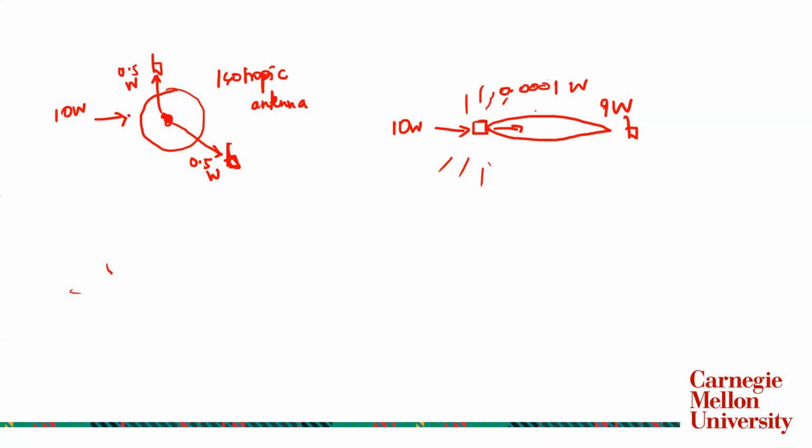Now that means that antennas have an ability to shape the power that you give them and focus it in only the directions that you want. So if I'm doing a satellite, and I'm an Earth station focusing on the satellite in space, I'm not interested in pushing my power everywhere. I want to focus it at the satellite where I actually need the connection. So that is what gives an antenna gain. It's not that it gets 10 watts and multiplies it by 2 or 4, because that would make it an amplifier.